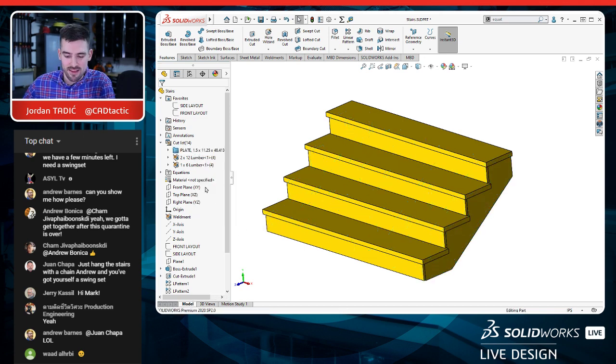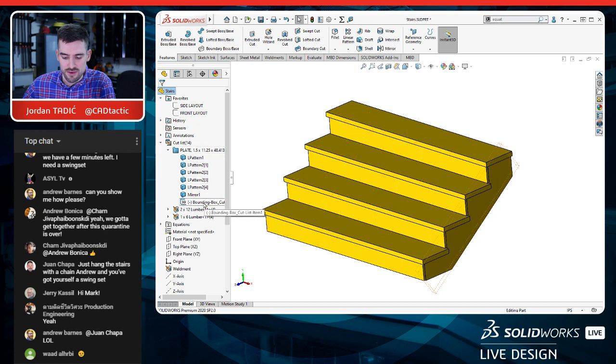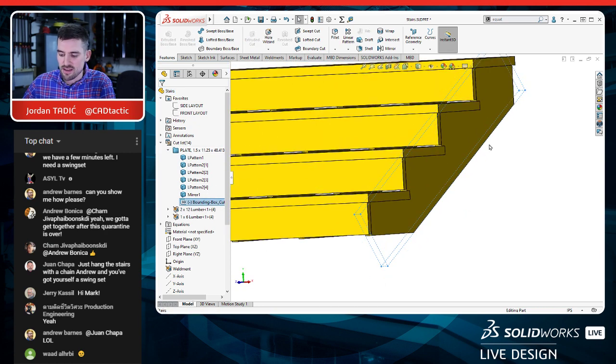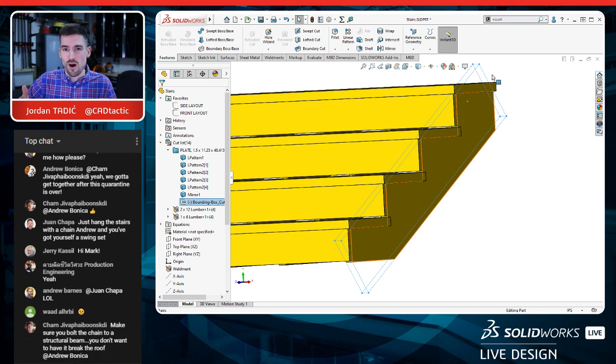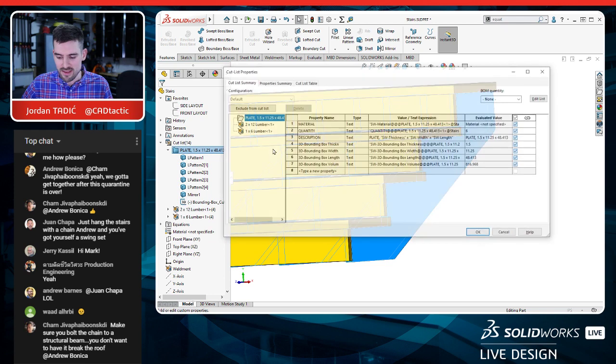Now, what actually happens in the background is if we expand this cut list folder, there's a 3D sketch that is automatically generated to wrap around the smallest box that could possibly fit around that geometry. This is essentially the raw stock 2x12, cut to the exact length that I need it cut to. So what SolidWorks does is, look at that, it already renamed it to plate, 1.5 by 11.25 by 48.413. That's the length that we need. So let's right-click and hit Properties and see how this is working.